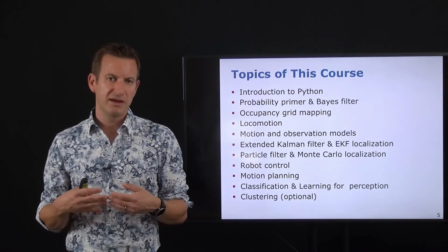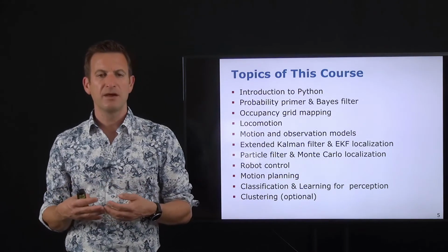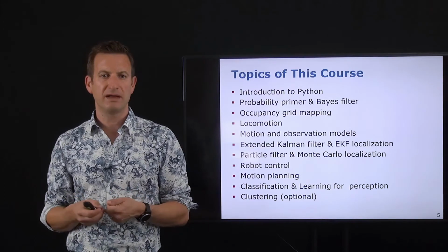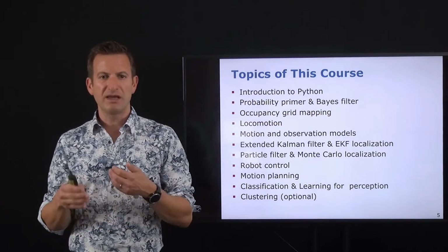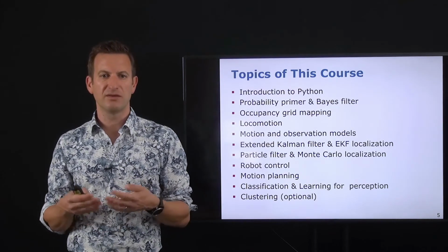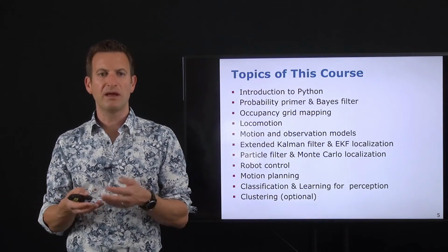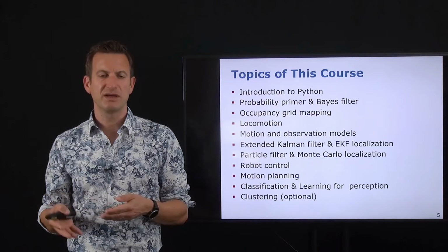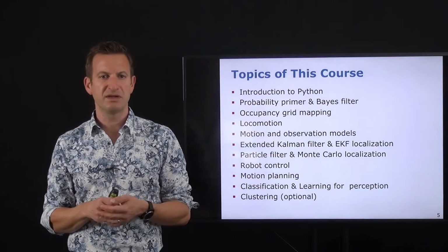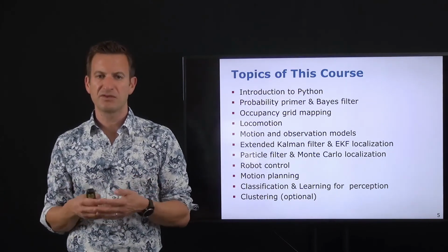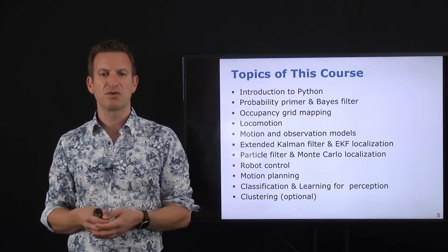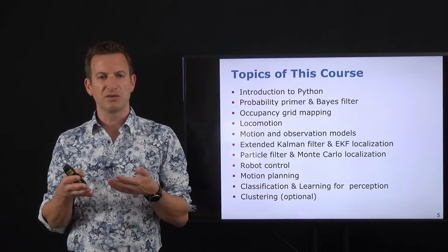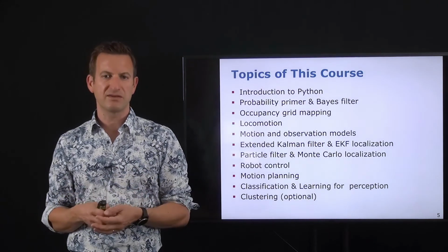And then we'll also look into control. This is done in the sense of executing an action. So how can we control the platform so that, for example, it drives on a certain trajectory or keeps a certain state? And this is then the lower level of the action selection, and the higher level of the action selection typically uses planning algorithms such as motion planning, for example, A-star or Markov decision processes, and so that is the framework for making decisions.